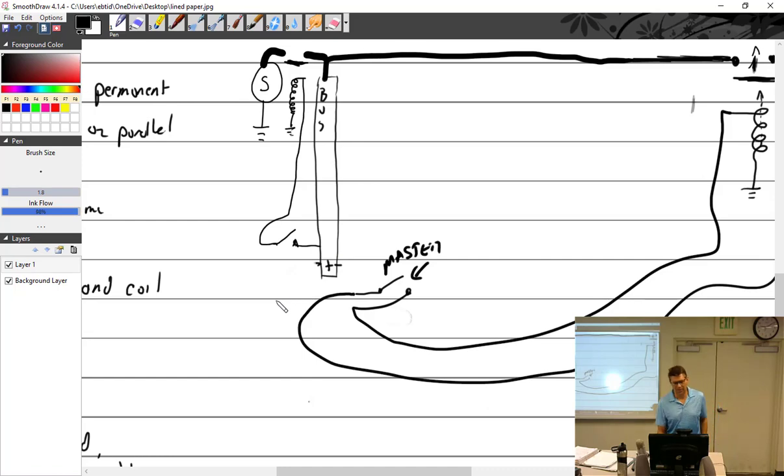Momentary. So I can just put it on the bus. So now when the master switch is on, the bus is live, and now that switch is live. If I push the switch, it's going to energize this right here, and the starter is going to go. If I turn off the master, the bus dies, and I can push the starter all day long.